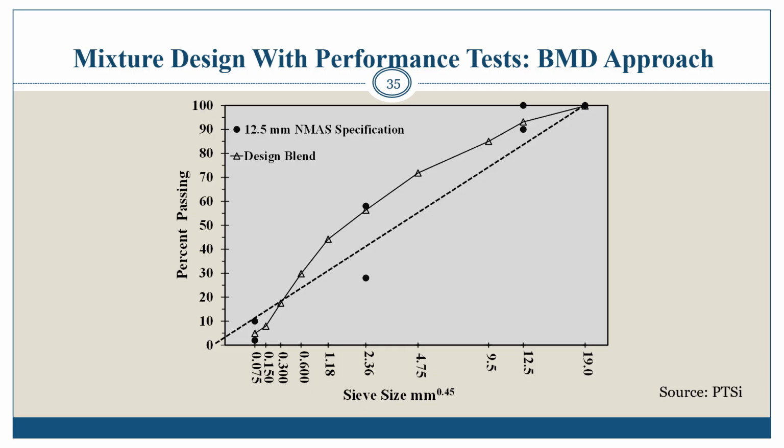We have selected a realistic example to look at dense graded asphalt. And in this case, very often you'll hear with GTR that you should avoid dense graded mixtures, and avoid dense graded mixtures on the fine side of the maximum density line. In this case, we decided to do exactly the thing that they recommend that we not do. So we chose a dense graded gradation that was pretty much on the fine side of the maximum density line. We want to see how that worked with different rubber asphalt GTR modified asphalts.